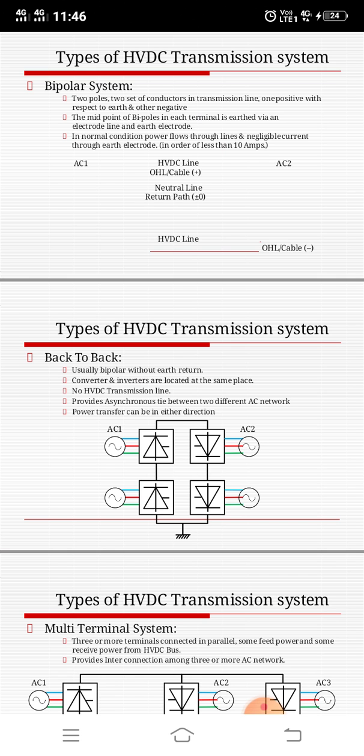Incidentally, the corona effect in a DC line is substantially less with the negative polarity of the conductor as compared to the positive polarity. The monopolar operation is used in the first stage of the development of a bipolar line, as the investment in the converter can be deferred until the growth of load which requires bipolar operation at double the capacity of the monopolar link.